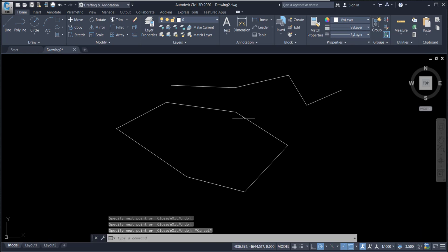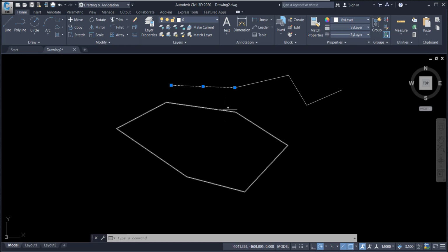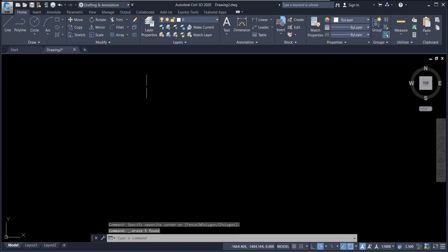So in this particular line feature, if I click on this polyline, everything will be clicked, right? But if I click on the line feature, it's just a particular section of the line that clicks. So the difference between the two is that when you click on a polyline, everything will be clicked. So it's good for extensive drawing like surveying drawing. If you're drawing with plenty of lines, you need a polyline instead of a line. So I just have to delete this.